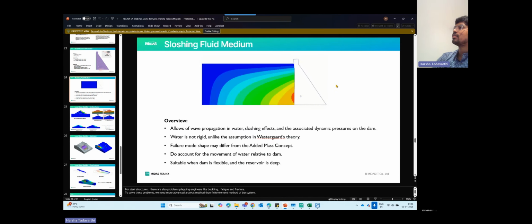There is some issue here because in the initial state, I had defined already sulfide. Now in this LC2 combination, I defined extra sulfide, right? So what I can do is I can simply go to this LC2, delete this option, delete the sulfide, and then press OK. And for the same sulfide, I can modify this from 1 to 1.2.